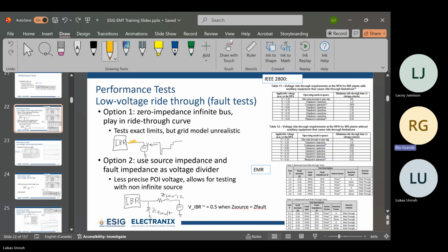Good. So a lot of times when you're doing a low voltage ride through test, you don't do that many that quickly. You don't often run into it, but if you have a manufacturer with a user-defined model that has a counter in there, you may see weird trips that you aren't expecting. But again, this wouldn't be in the generic level.